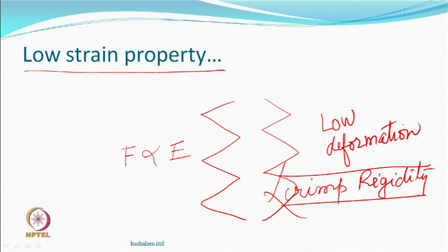And if you are lucky, let us say this is CO and this is NH and then maybe CO somewhere, etc. If they come very close, then they make hydrogen bonds. So, if the possibility of forming intermolecular hydrogen bonds is high because of the molecular structure itself, then the modulus of that particular fiber could be high.